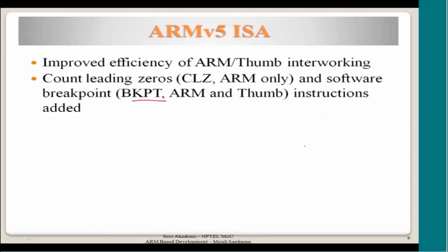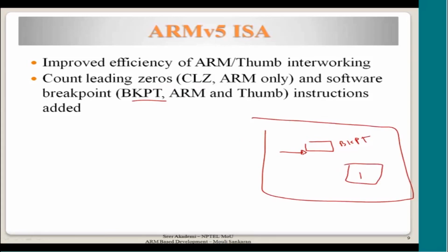And then breakpoint is another instruction. When you are debugging inside the assembly, you can put an instruction called breakpoint. What happens is the execution stops, and there is a debug unit inside the ARM architecture. Inside the SoC there is a debugger, as I mentioned; some hardware is integrated for emulating, and some debugging capabilities are built into the hardware. So when it encounters the breakpoint instruction, the control is passed on to the debugger.